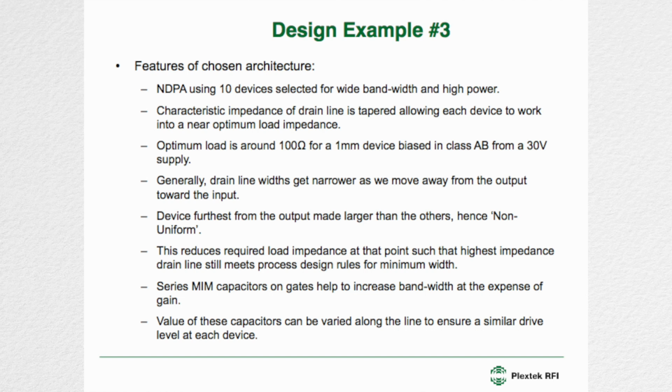And we introduce series MIM capacitors on each of the gates. What this does is allow us to use slightly larger transistors for the same upper cutoff frequency, which increases the output power at the expense of gain. Like all things in design, it's a trade-off. And we can vary the values of those capacitors to ensure a similar drive level at each device.